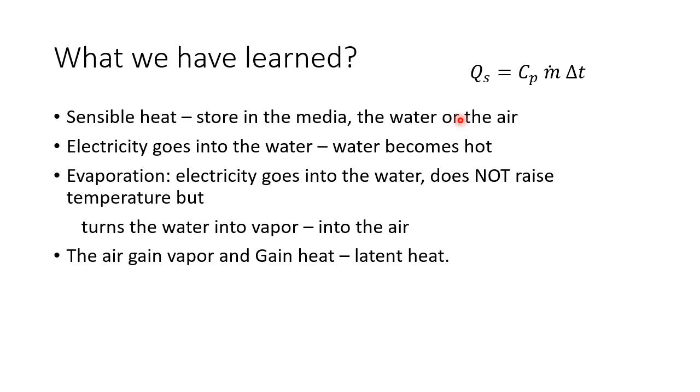So water lost energy, and the air gains energy, but the energy gained is called latent heat. And the latent heat is calculated as QL, latent heat, equals the heat of evaporation multiplied by the mass flow rate. Here, we need to be careful.